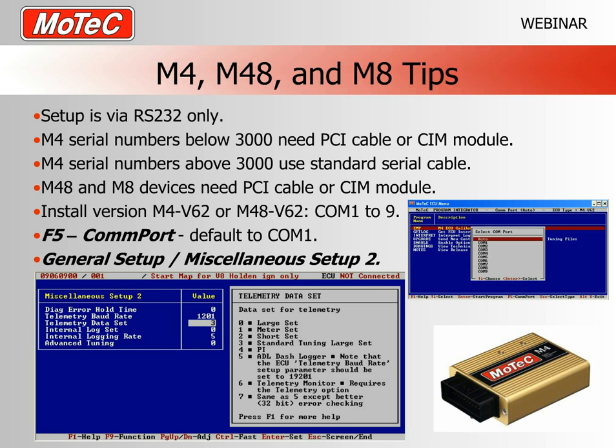Okay, so the telemetry baud rate is the number which defines the bits per second. If you are in this program and you select that, you'll see a help screen which gives you some extra help on what these numbers mean. If it's a number like 1201, it basically means 1200 baud with one stop bit. There are a number of other variants as well, such as 19201, which is 19,200 bits per second with one stop bit.